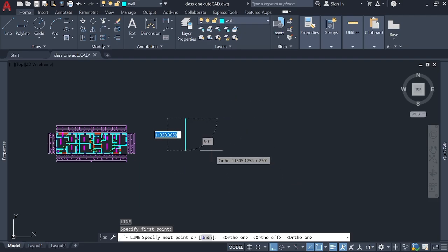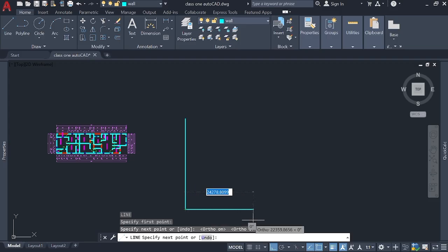Talking about those two boxes, we've not inputted any dimension yet. Let's draw a straight line just like that. Then if you keep on clicking, it will be telling you indicate next point, but I just clicked only once, so I've gotten my straight line. I indicated the first point here, I clicked here and I clicked here, so I've gotten a straight line. See, so I can exit this command by pressing what? Escape.